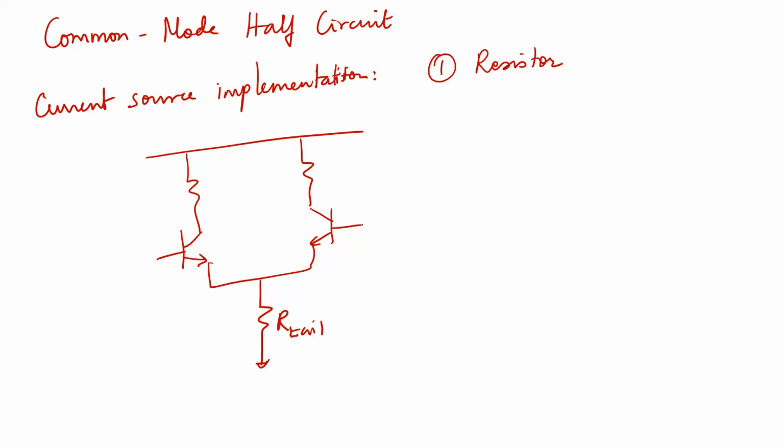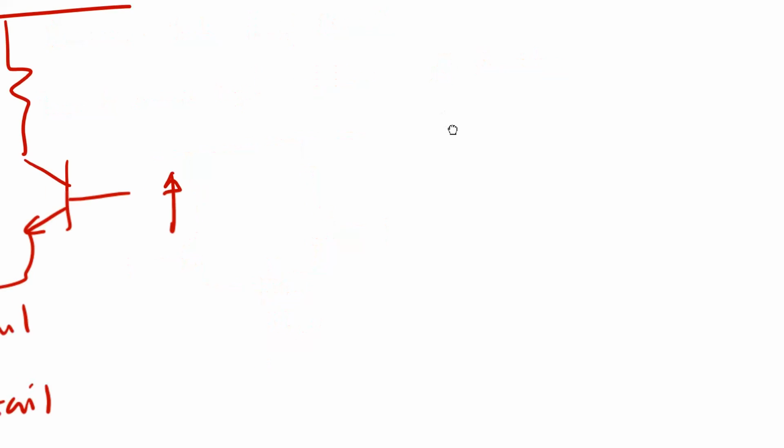Now what happens is basically that if you look at this circuit, the common mode part of it, if the common mode signal increases on both sides, this node P will also increase. Okay, notice it does not react to differential signals. For common mode signals, it will react. Okay, now automatically this is that negative feedback action that we have been talking about for quite some time, right? And so this emitter resistor is going to control the current and keep the I tail which is flowing here to be fairly constant. Okay, so it's a kind of a poor man's current source in this context, right?